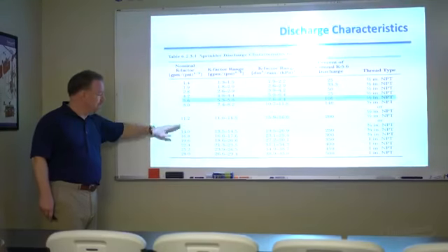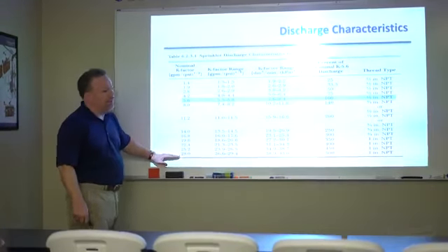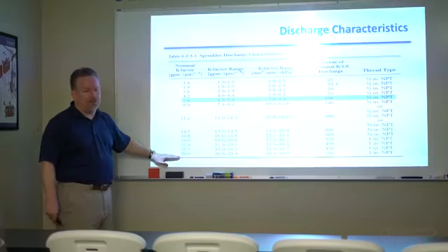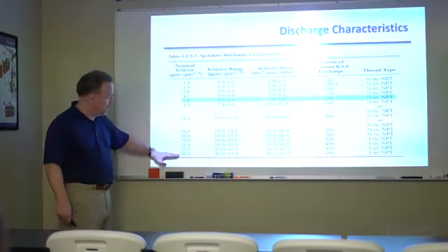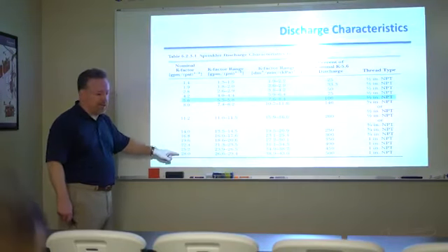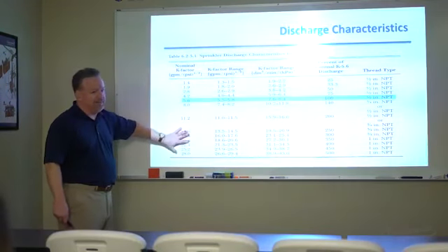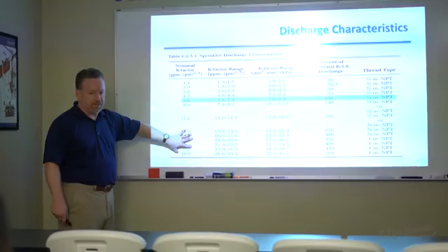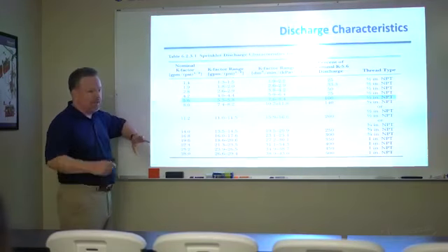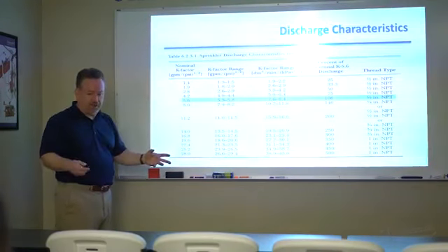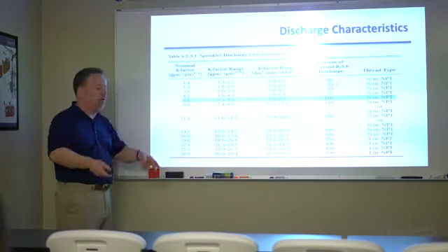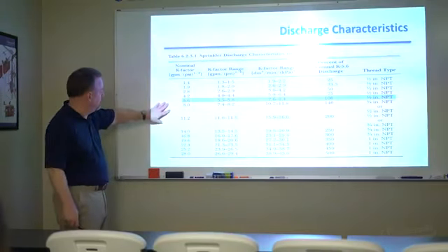All right? These are basically used for high challenge storage type fires. When you get up into these ranges, these are the type of sprinklers that you'll find protecting storage occupancies. Mainly because fires tend to grow very fast in those occupancies, and we need to get water down through that fire plume very quickly.